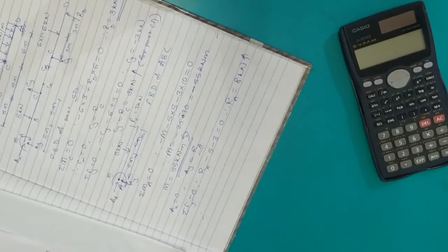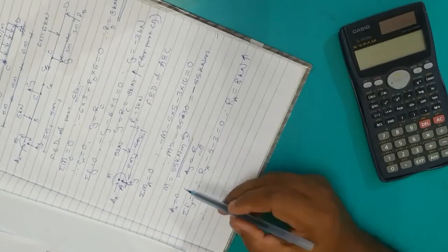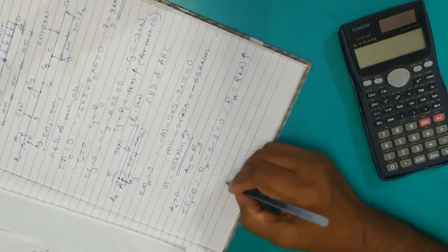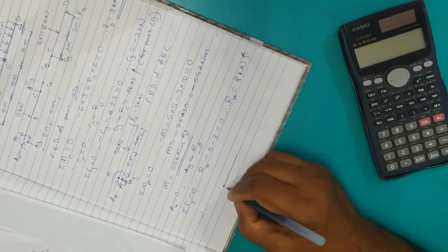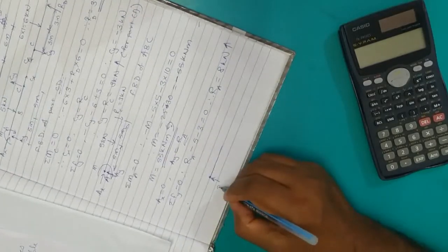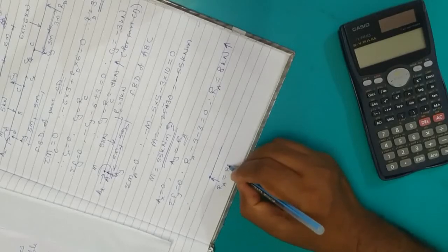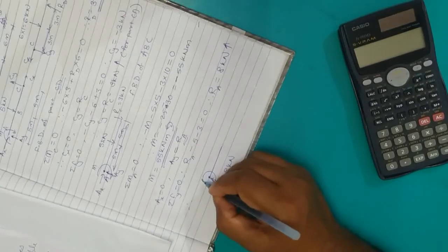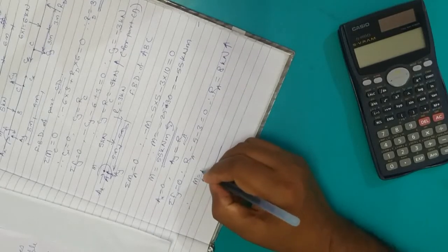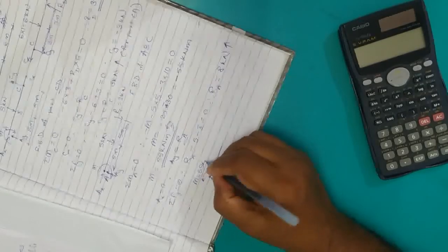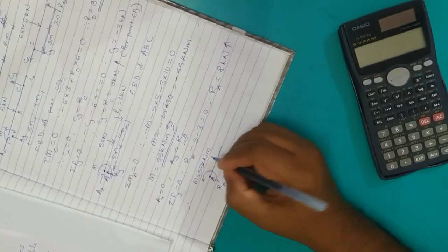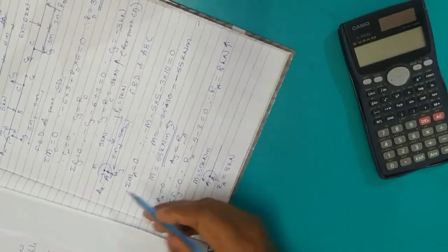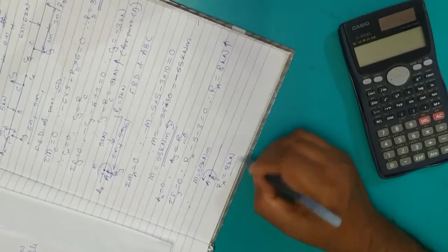So at the end, at point A, if I have to show all the reactions existing for the fixed support, I can show it this way. If this is the end A, we have Ra, which is 8 kilonewton vertically upward, and then we have a moment which is anti-clockwise with the magnitude 55 kilonewton meter, with the rotational sense as we checked, anti-clockwise. This is the total reaction existing at point A, and that is our final answer.